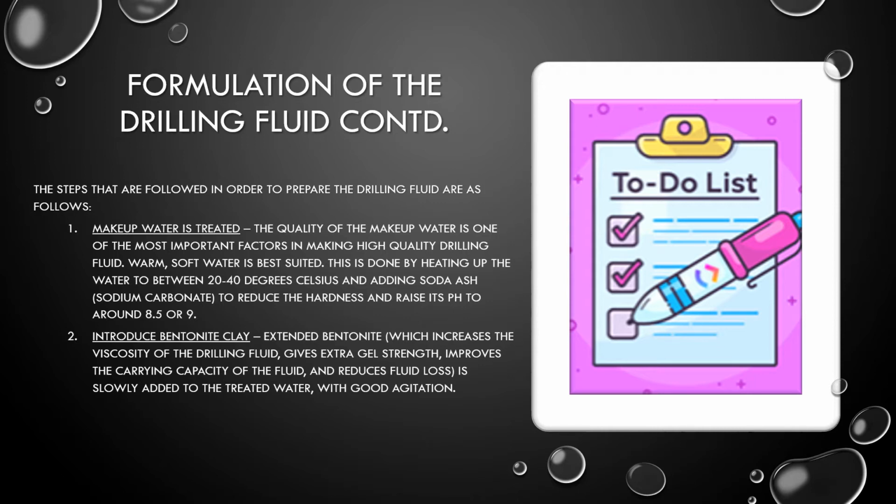The next step is to introduce the bentonite clay. Extended bentonite, which increases the viscosity of the drilling fluid, thus giving extra gel strength, improves the carrying capacity of the fluid, and reduces fluid loss, is slowly added to the treated water with good agitation.